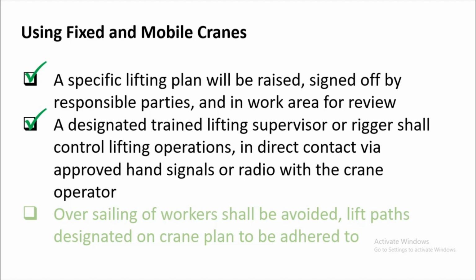So make sure you have a dedicated lifting supervisor on your lifting operations, so that this supervisor will check if the lifting operation is in control and in proper safe operation, and make sure that all the riggers are also competent for their job.